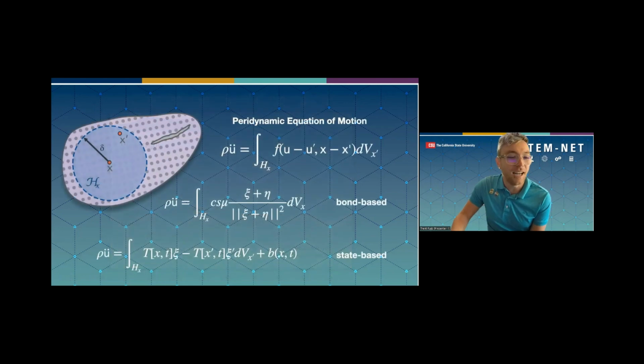And to implement these models, we have to summon the power of peridynamics. It's a recently new branch of classical continuum mechanics, early 2000s recent. So it's pretty new, which treats objects as a continuous mass rather than discrete particles. And this is actually pretty huge, as previous models seeking to model such corrosion maintain costly iterative meshing and remeshing schemes, which also happen to be discontinuous at the crack surface. Oh, and it also doesn't allow for natural crack propagation.